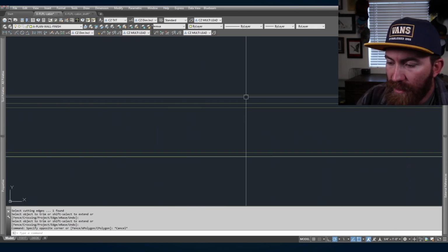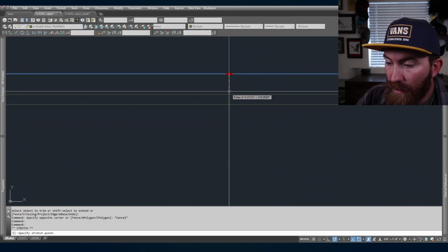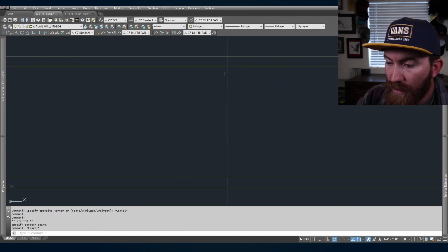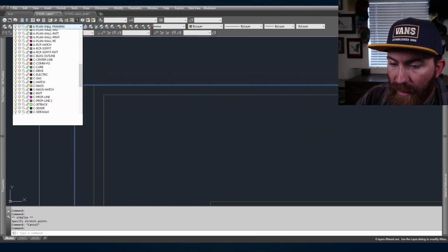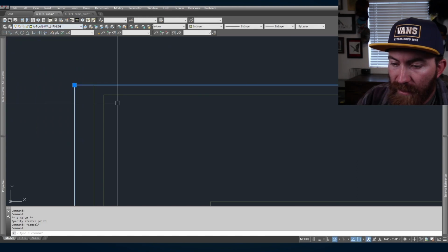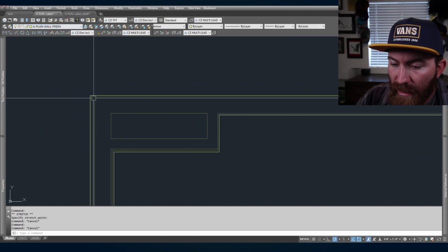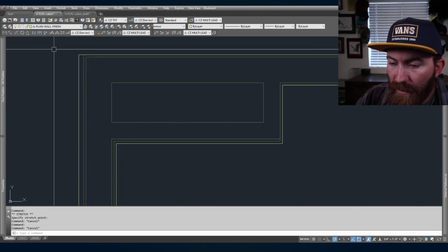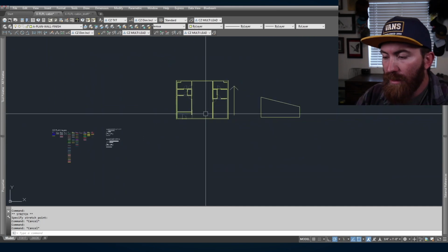So that metal roof just goes on top of some sheathing and some underlayment. So I'm pulling this line down so it's in line with the sheathing. That way when I move this to my finish, I've got my 1 inch stucco finish, my 1/2 inch siding, and then from here is where I put on my metal siding. So that's why there's that weird little jog.